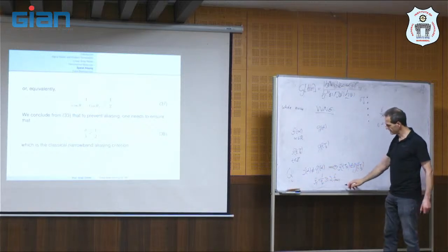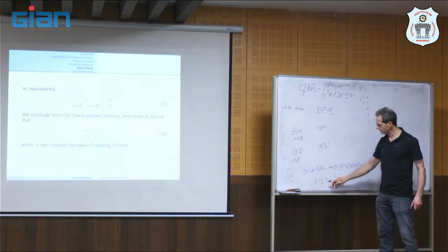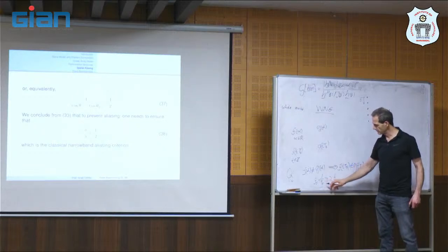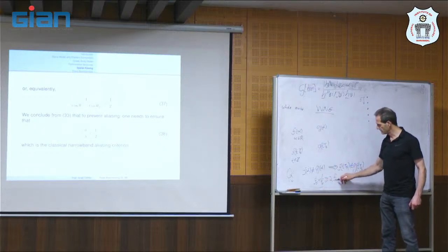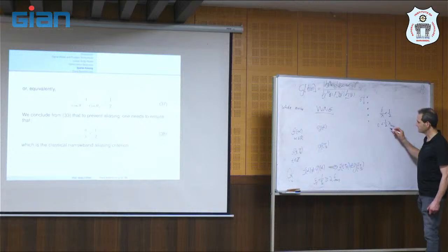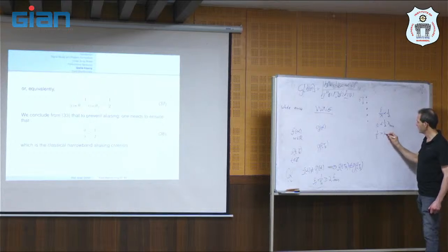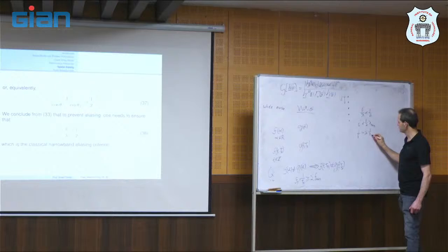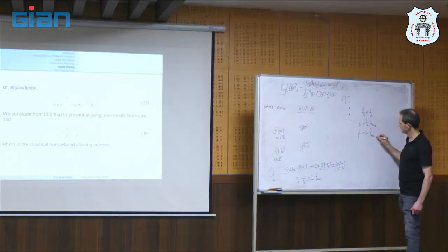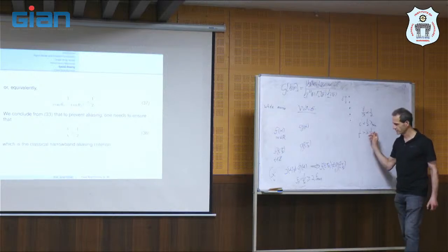So you see the similarity with temporal sampling. In temporal sampling, the sampling frequency is larger than twice the maximum frequency in the signals. Here we have the minimum lambda, so we can say that 1 over delta, the spatial sampling, is larger than twice 1 over lambda min, which is the maximum spatial frequency in that direction. So it's very similar.